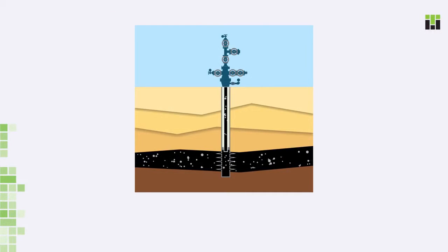In reality, open flow caused by hydrostatic forces only happens on rare occasions. Mostly, open flow is caused by natural gas that is contained in reservoirs along with oil. In oil reservoirs, their bubble point pressure is equal to reservoir pressure. Gas serves two purposes. In the reservoir, it forces oil out, and in production tubing, it lifts it up to the surface.